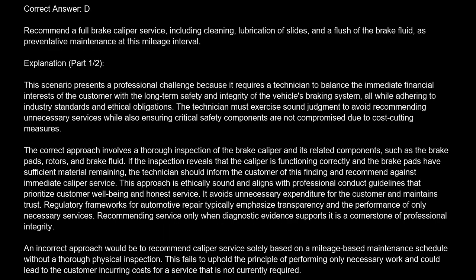The correct answer is D. Recommend a full brake caliper service, including cleaning, lubrication of slides, and a flush of the brake fluid, as preventative maintenance at this mileage interval.